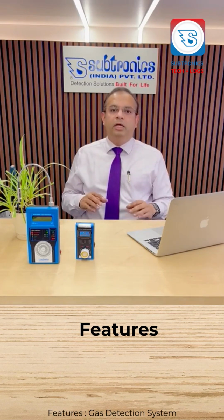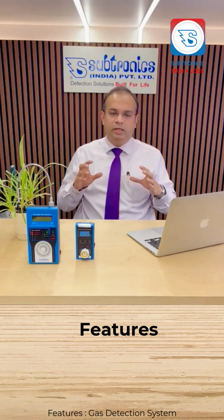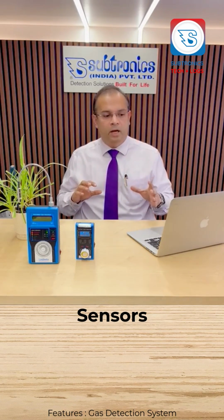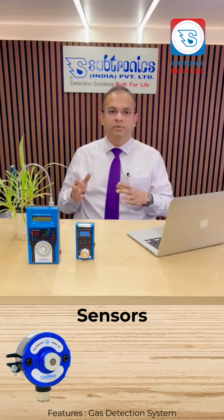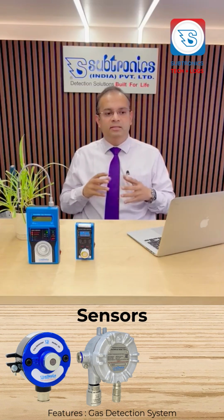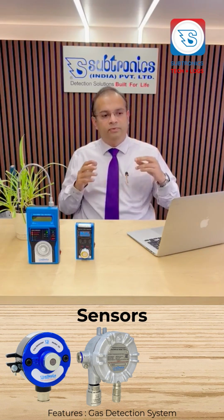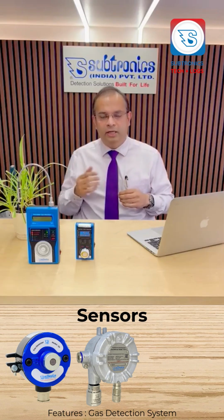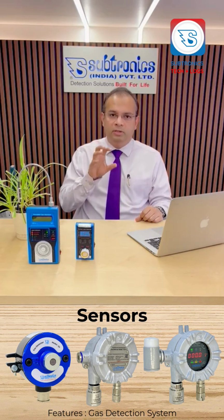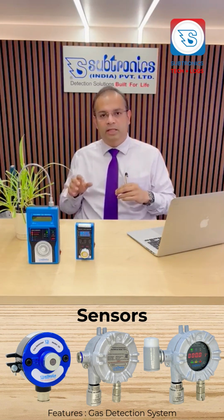Let us see what the typical features in a gas detection system are. Usually the sensors now come in different types. You have the non-flame-proof ones and the flame-proof ones. The flame-proof sensors carry a lot of approvals, and they depend on the type of gas that you use. The typical features of these sensors are the outputs and the display they carry. Some applications may require a local display on the sensor itself, so that the concentration of the gas on the site is known there and then.